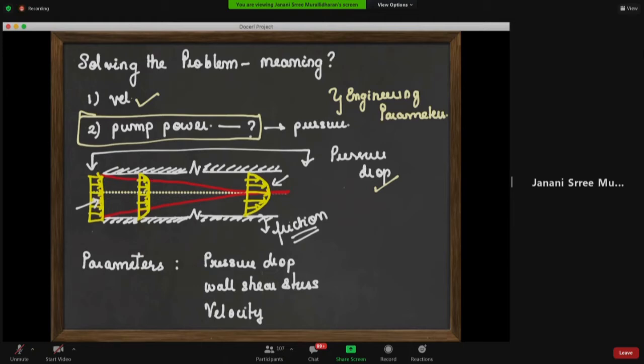So this pressure drop needs to be provided in order for flow to happen. So why does the pressure drop happen? Let's just understand that a little bit. There's flow that's entering, and there's going to be friction at the wall, maybe a few other head losses because of pipe turning in and out. And hence there is a balance which has to be reached.